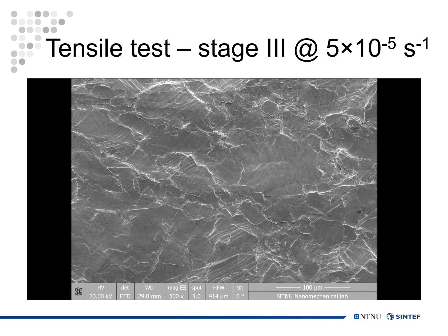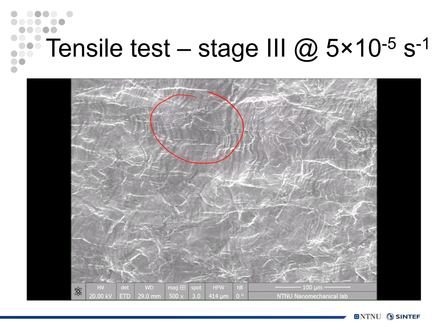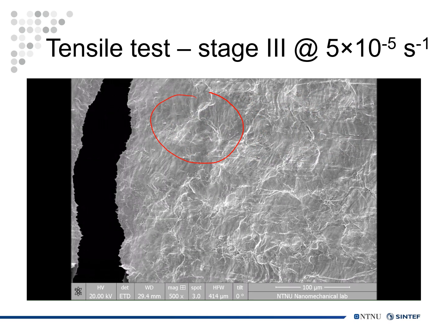The final stage continues until the final fracture. The grains start to rotate in order to accommodate the high strain levels, and the slip bands are aligned vertical to the loading direction, and the fracture follows the direction of these deformation bands. Though we saw damage at grain boundaries and precipitates, the final fracture did not happen there.